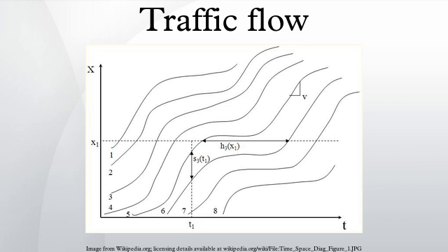Road junctions. A major consideration in road capacity relates to the design of junctions. By allowing long weaving sections on gently curving roads at graded intersections, vehicles can often move across lanes without causing significant interference to the flow. However, this is expensive and takes up a large amount of land, so other patterns are often used, particularly in urban or very rural areas.